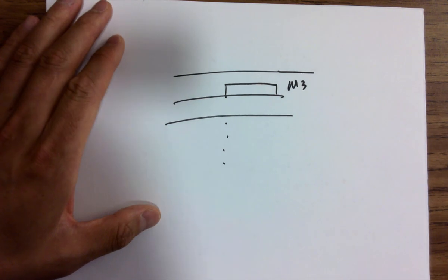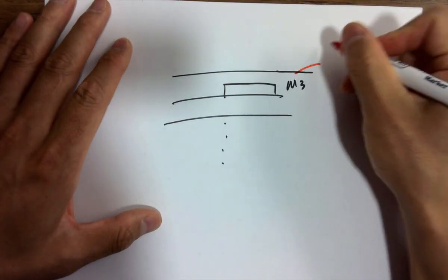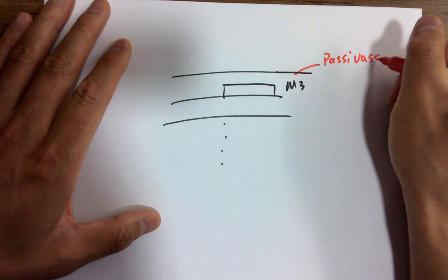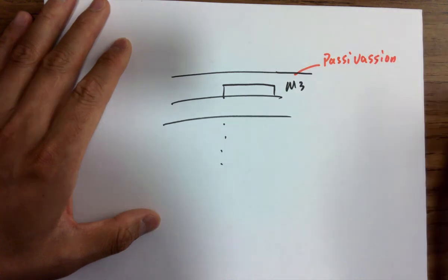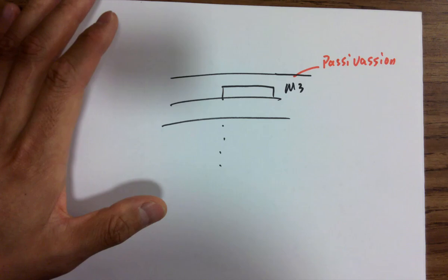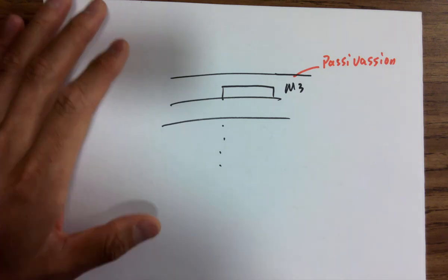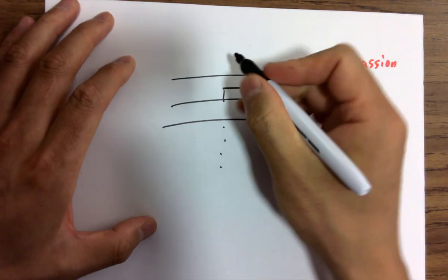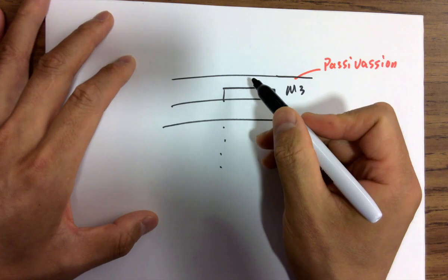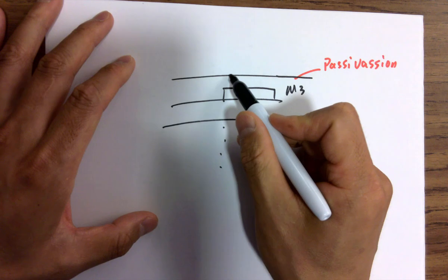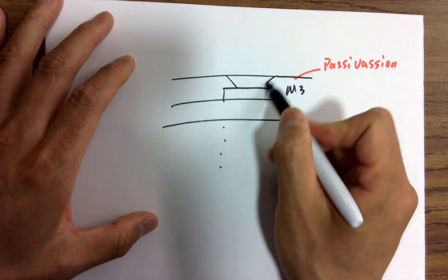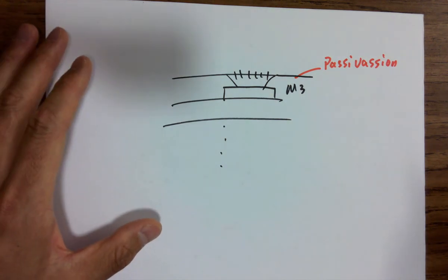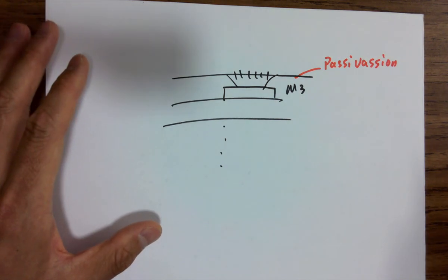But actually the top insulation layer is a bit thicker. They call it passivation layer. Passivation layer. So passivation layer is also insulation layer, and there's a component in electrical VLSI in the library, and you place it on the top of Metal 3, and it's gonna open up the passivation. So this will be removed during the fabrication process. So it's gonna be opening on Metal 3.